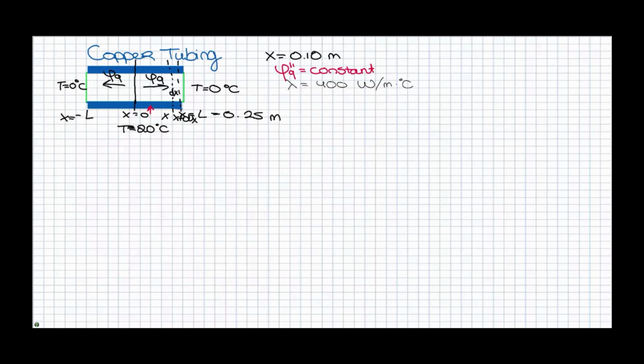So now you can set up the energy balance. The energy balance has to be set up over the small part dx, where the heat is transferring through the surface and heat is produced, which gives the following equation. You have, of course, an energy balance. The heat that flows in at point x, so here, minus the heat that flows out at point x plus dx.